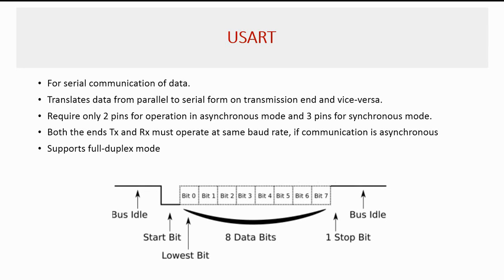Our first microcontroller, the 8051, has one serial communication channel, that is UART, Universal Asynchronous Receiver and Transmitter. As communication is not synchronous, the receiver and transmitter operate at the same speed or same baud rate, and the data byte is framed between the start and stop bits to indicate the start and end of the data byte. And you cannot connect more than 2 channels on the UART bus if we want a secure transmission.